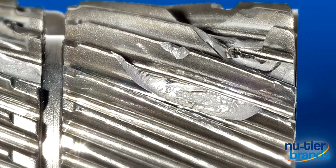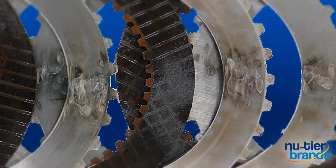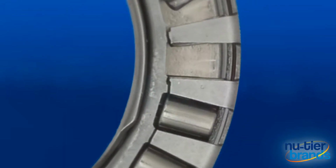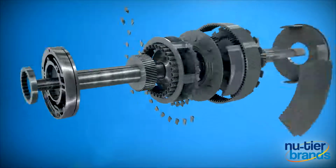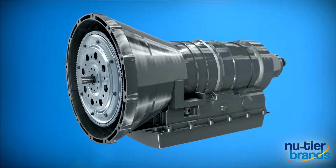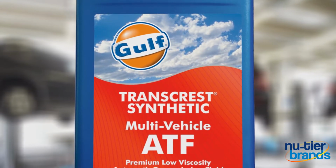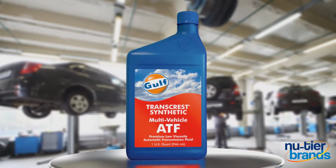And using the wrong fluid can be catastrophic. At worst, you can cause excessive wear in pumps, gears, and bearings, leading to permanent damage and the need to replace your transmission. A single mechanical failure could disable the vehicle entirely. The automatic transmission is one of the most complex components in your car, and it's also one of the most expensive. So follow the manufacturer's suggested service intervals and use only OEM quality parts and the OEM recommended ATF to help maintain the life of your transmission. You'll be glad you did.